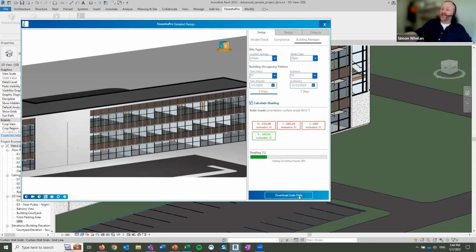So shading, in the case of this building, being my shading devices, but also if I'd massed up a number of buildings in that environment, we may have a 20-story tower, 30-story tower across the street, which is significantly shading my southern facade. Therefore, the amount of glazing isn't going to hugely impact my solar heat gains and my cooling loads. I need to understand that.